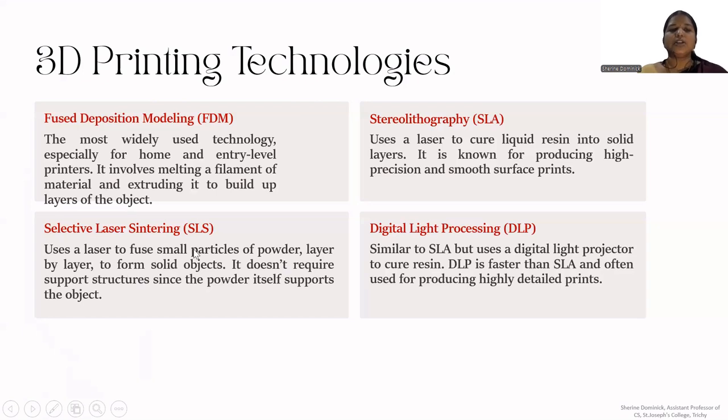So this object takes the raw material in the form of powder, and this powder has a binding agent added to it, and using the laser, we fuse this material along with the binding agent and we send it into a mold to develop the 3D printed object.